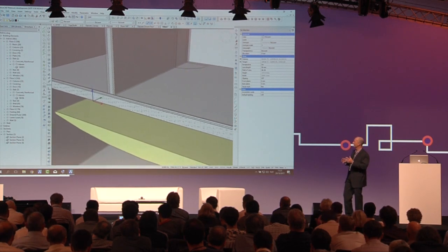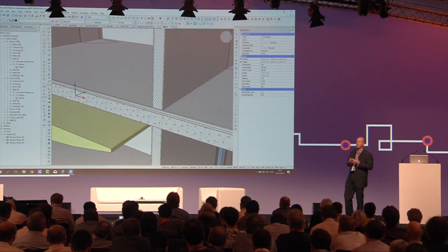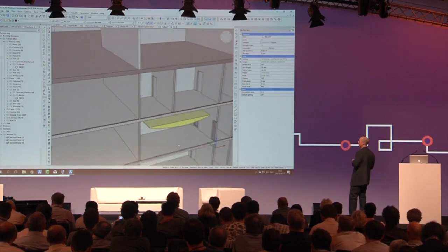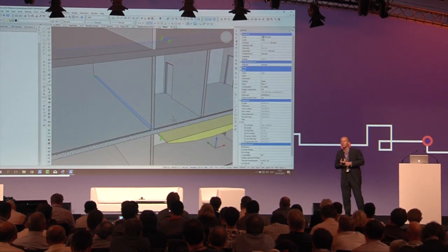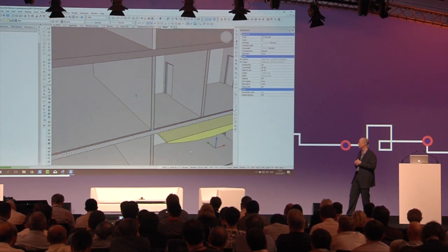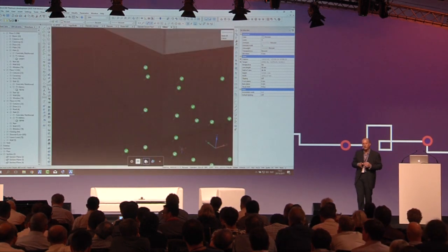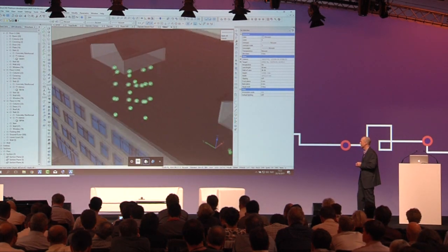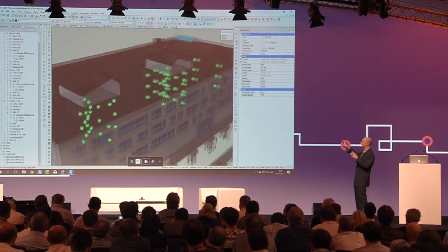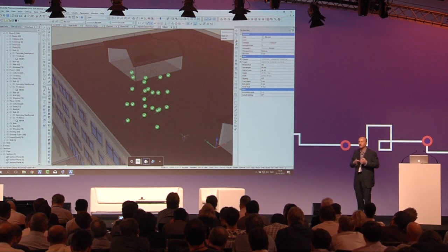And if we look around, with the interior walls that we have in the cores that are set up on this design, there's going to be a lot of opportunities where we could apply that same connection. So again, we'll just select the wall and select the floor that meet at the connection that we want. And then we can do BIM suggest, run that again. Again, it's searching the overall model in terms of connection options. We're taken to this interactive mode. And now we've got over 40 connections that we should consider and take a look at.